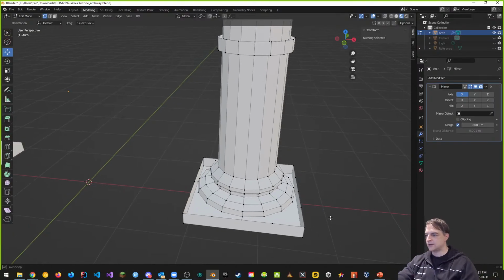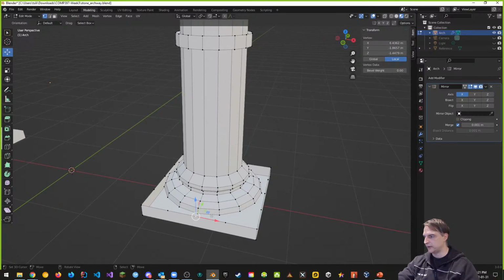So how do you connect these? You just connect the vertices. So you go something like right click there. It's a little bit of manual work, unfortunately, but it is what it is. And you kind of connect it with that one, and you press F, and then do this one and F. And then for the actual faces, and this is where the faces might get messed up, you're going to Control Tab when you do it.